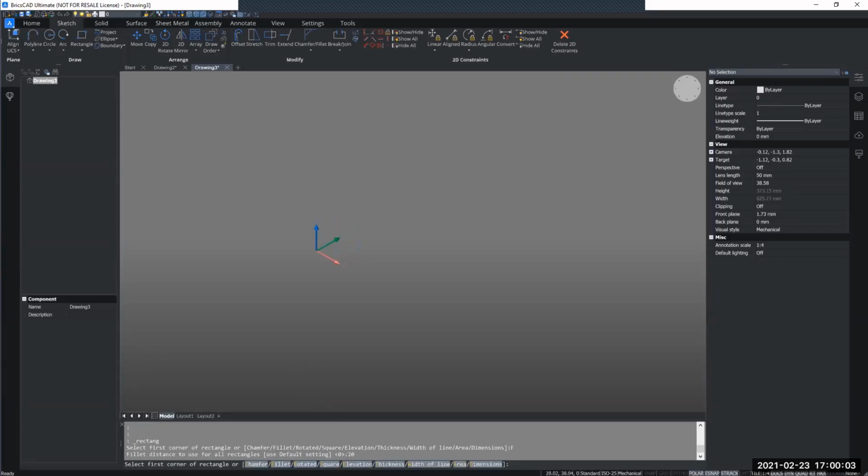And now I want to start my sketch in the origin point of the drawing. I can do that by clicking in the origin, but I can also do it by typing 0,0,0 in the command line, and it will start my sketch in the origin. It's quite an easy way to start sketching from the origin, and it's something I use quite often.